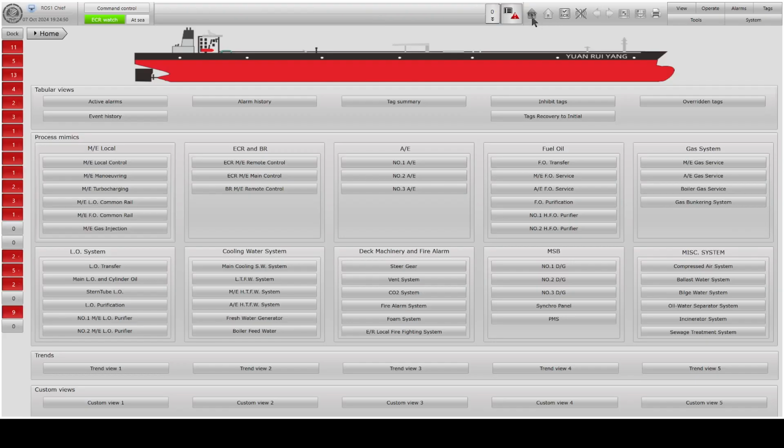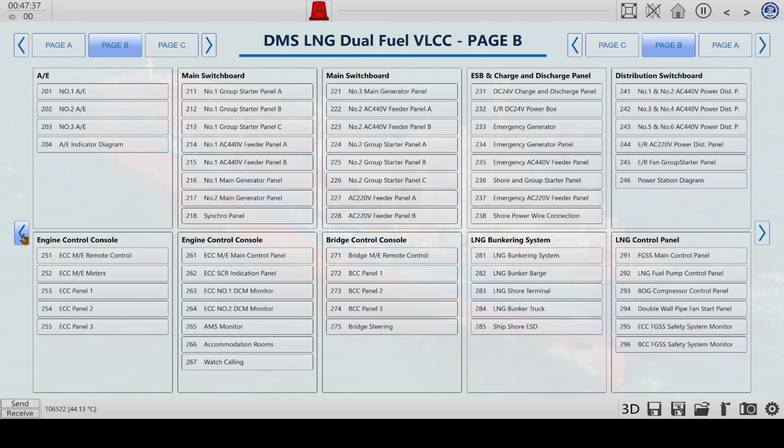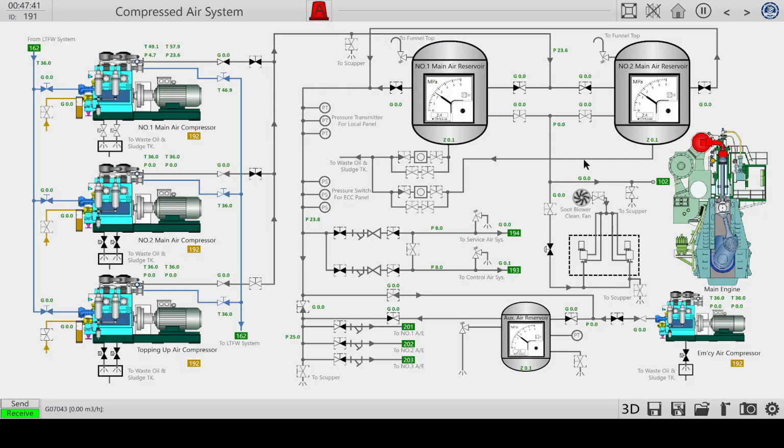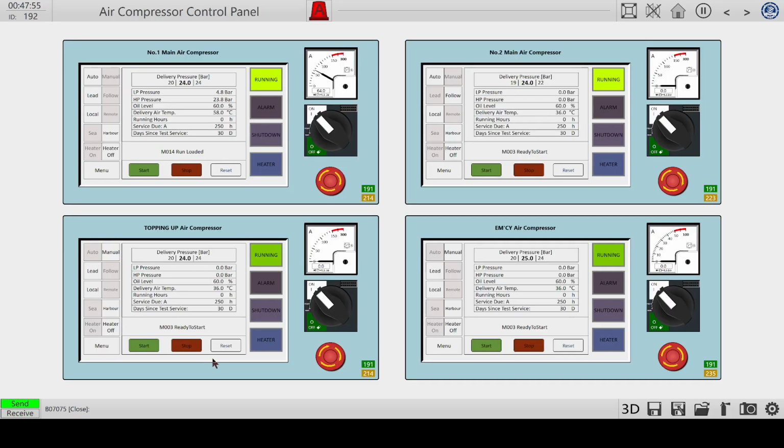We'll acknowledge it. Reservoirs are filled enough, so the second generator is stopping. Let's use the top-up generator compressor to fill when needed by putting this one also in auto mode.